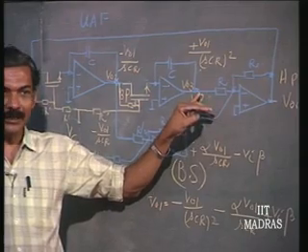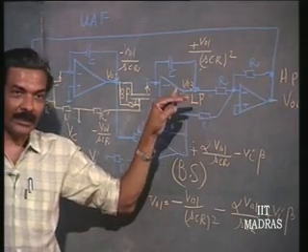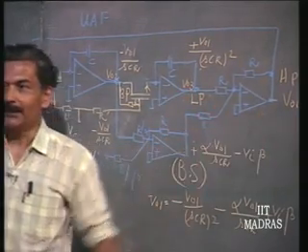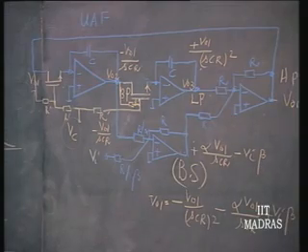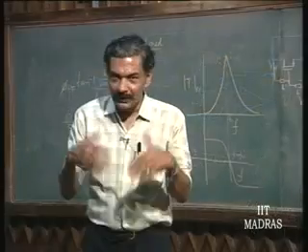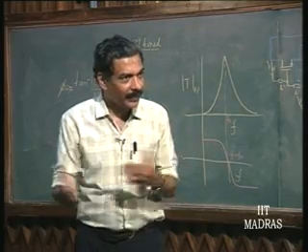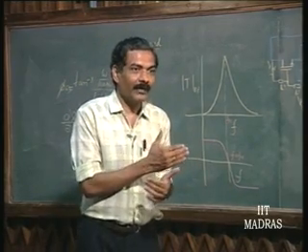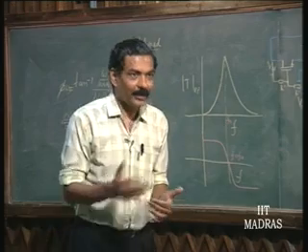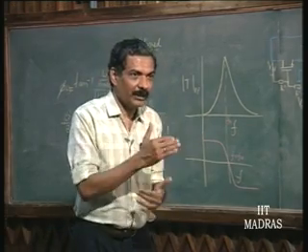Therefore, if we use an additional phase shift of 90 degrees, that means either low pass or band pass in this structure, we can use it in combination with our phase detector that we have learnt to find out how exactly I have to shift the frequency in order to tune it exactly to the incoming frequency.